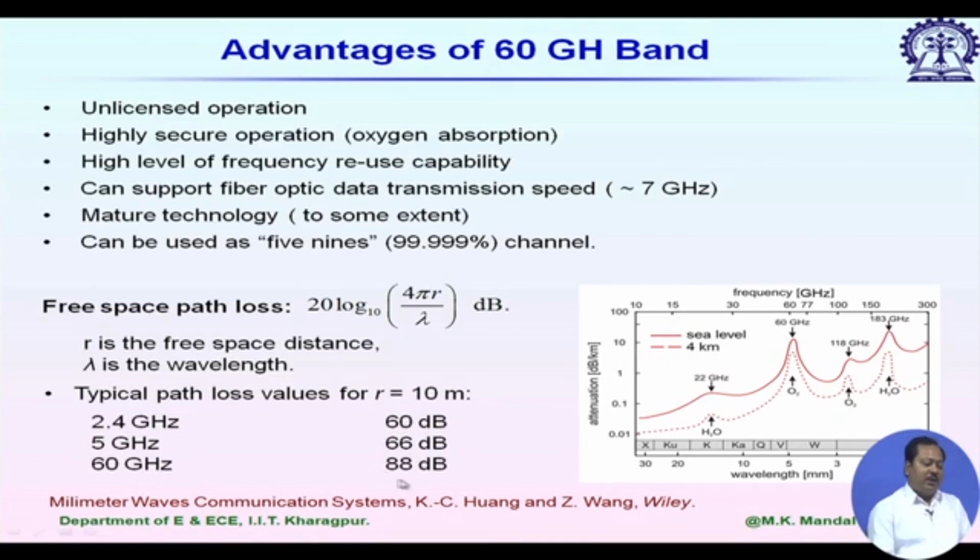In this expression, we did not consider the absorption due to oxygen molecules. No atmospheric attenuation is here. Just because of the smaller lambda value, this path loss is increased from 60 dB to 88 dB, 28 dB higher.